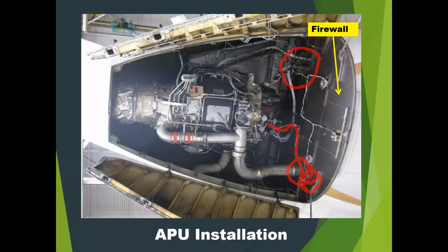And the reason for that is this chamber, when those doors are closed, they also have a rubber seal on them that's shown along this edge. So when those are closed, it creates a sealed compartment. And so if the APU were to catch fire, we can fill this space with halon in order to put it out using a fire bottle. Later on we'll look at fire prevention on the aircraft, fire prevention on the APU, and it has its own dedicated fire bottle in order to flood the space with halon to put out a fire if you were to have an APU fire.